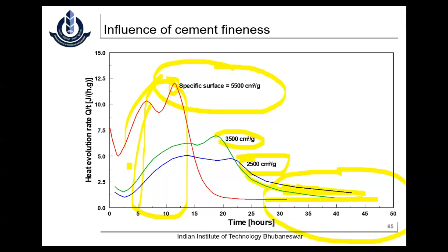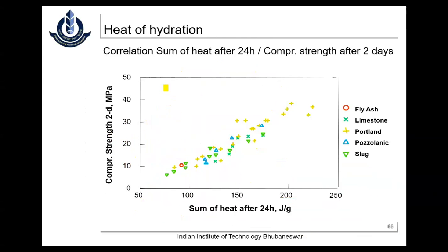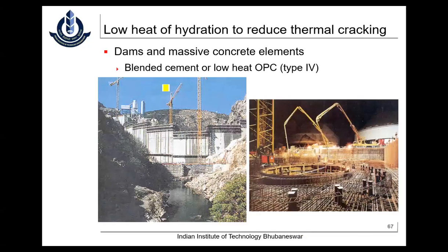The first very few hours, what the cement hydration takes place, that is a big concern for any manufacturer, any end user actually. Because if you have a very high fineness, you see that this is what the heat evolves, and definitely there will be a lot of cracking. Okay, so that we need to look at. I'm not going to touch much upon the heat of hydration. And the low heat of hydration, especially for mass concrete structures, which was already covered, you can use that.